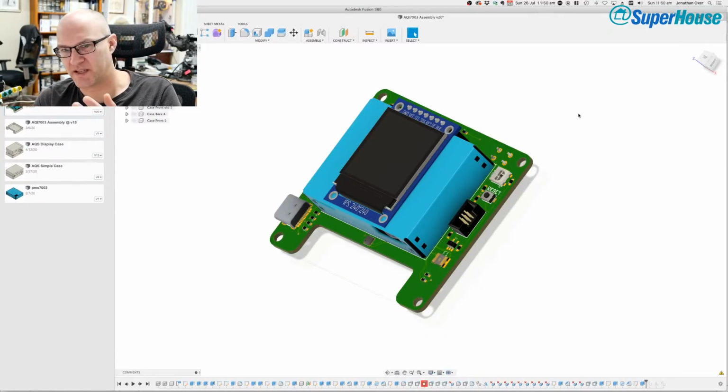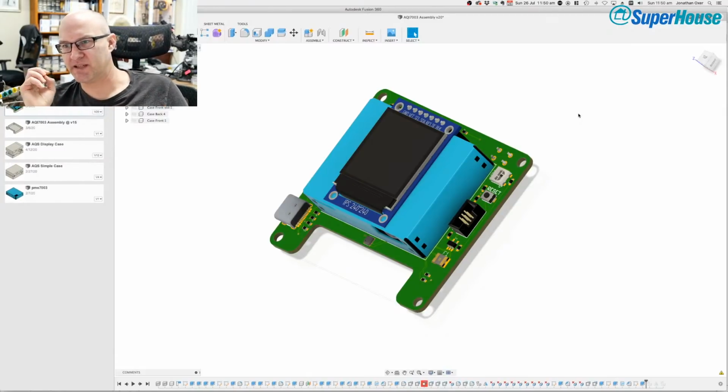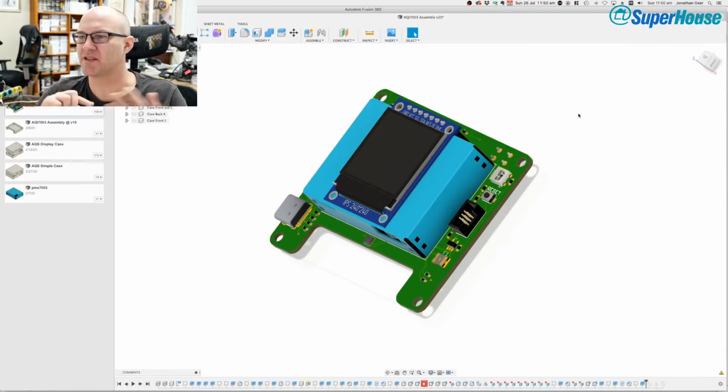You start with specifications, then you do a schematic, and on big projects the schematic will actually be designed by a different person to the person that does the PCB layout. So someone designs a schematic, and they'll put notes and hints in the design about things like put these decoupling caps close to these power pins. But they then just send the schematic off to a totally different person, and that person receives the schematic, looks at the notes, and then lays out the board.